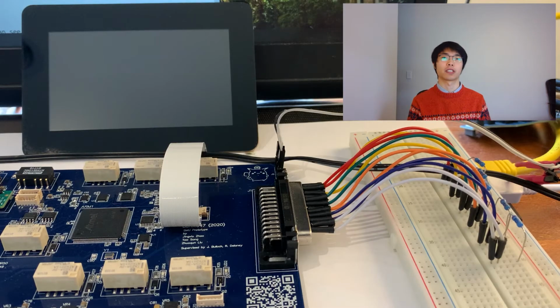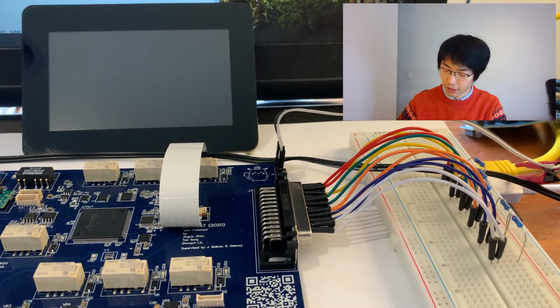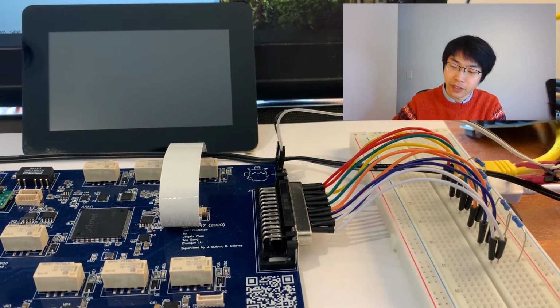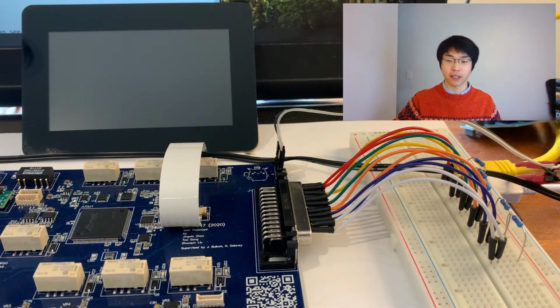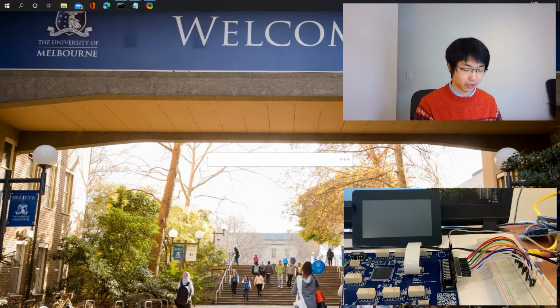Welcome to Neuro's desk, and I'm going to give you some demonstration about what our SMU can do up to the recording date, which is the 6th of October 2020. Our SMU basically can measure 5 different resistors and calculate the contact resistivity from the measurement. As you can see here, we have 5 resistors set up on the breadboard to simulate the practical use case. And we are going to use a terminal command to communicate with the SMU, as it's the only way that we can talk to it bi-directionally.